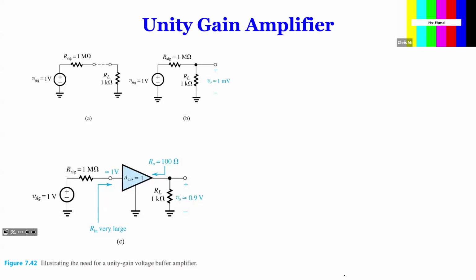So that's why the common-source MOSFET amplifier is important, because the gate is open in the small signal equivalent circuit. Whatever the resistance of the signal source, it doesn't matter, because the input resistance of the MOSFET is infinity, right? So yeah, that's the circuit.